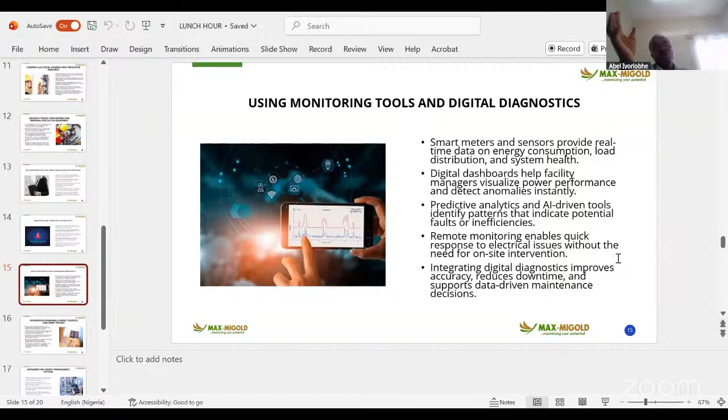Maybe over time you see that I've not really utilized the 200 kVA that I have on my side. Our load has been between 80 and 120. That shows that you don't need 200 kVA in your estate now. When you talk of diesel, what the diesel price is all about now. So you have real-time management, decision making. So that's what you present to your management.